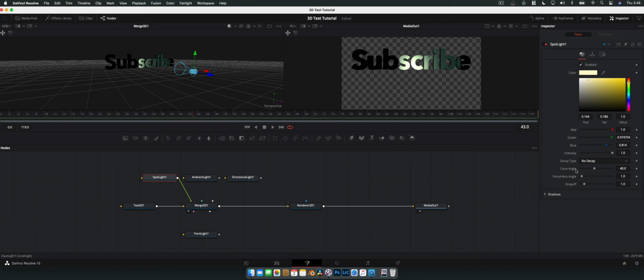But we can also go down here and we got the cone angle, and we can increase that or decrease that, make it a very, very sharp light. And we can also change the penumbra. Now the penumbra is basically, I guess, how harsh the edge of the light is. So if I bring that to none, you can see we have this very harsh edge here. But then if I increase that a lot, you see we get this really soft fall off there. But at the moment, we're just gonna play around. We move it in, move it out, and the further we move it out and relocate it, we can light an entire scene. And like I said, it acts just like a spotlight would in a theater of some sort. So let's disable that and plug in the ambient light.